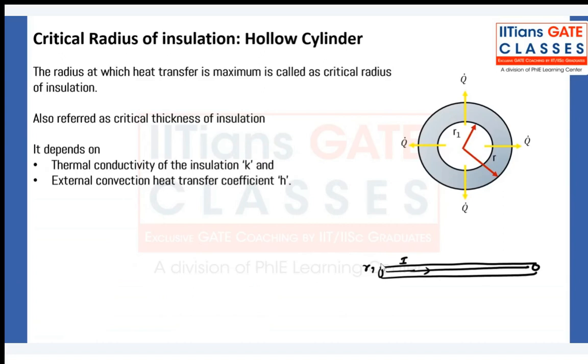If you increase the temperature, it basically degrades the performance of the chemical reactions. The chemical reactions take place at a particular temperature. If you are not removing heat and the temperature is going up, then it is going to negatively affect your chemical reactions. So what do you need? You need to maintain a constant temperature, so you need to maximize the amount of heat transfer.